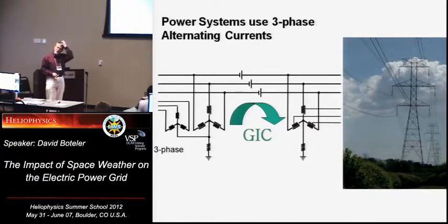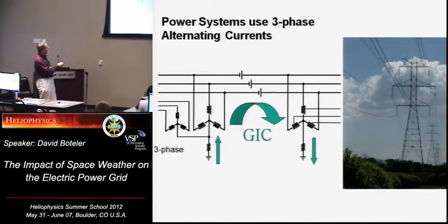Now, this is very significant because this influences the path that the GIC, geomagnetically induced currents, can take. So the currents can go along the lines and flow to ground or to and from ground through the transformers at the substations. And so you get a current flowing in at one substation, along the lines and out at the other substation. And we'll get into more detail about exactly where it flows later on. But that's the basic principle of the AC system and the features that affect the geomagnetic induction.